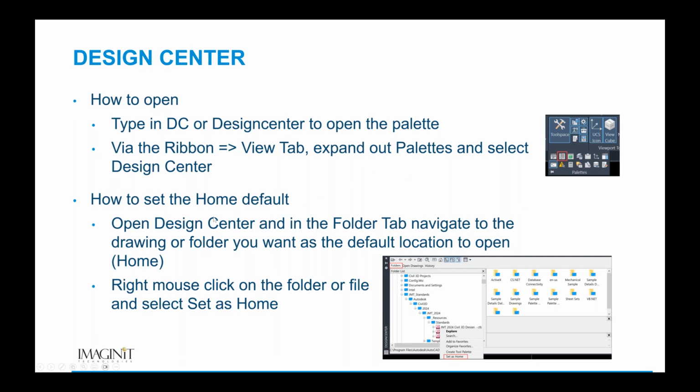The cool thing too here is that you can actually set a home default. So if you open up Design Center and in the folder tab, navigate to the drawing or folder you want as the default location to open as home, you simply right mouse click and say set to home. And every time that you open up Design Center, that's the first place it's going to take you, is to your home. So you can always go right to your drawings that you use.